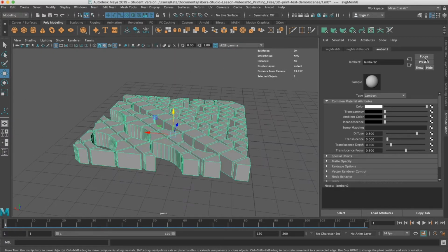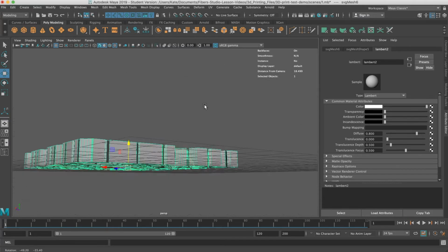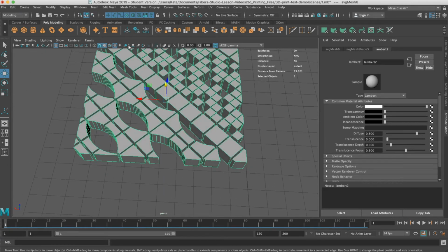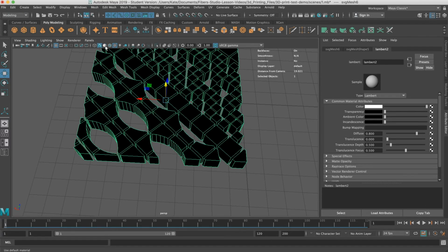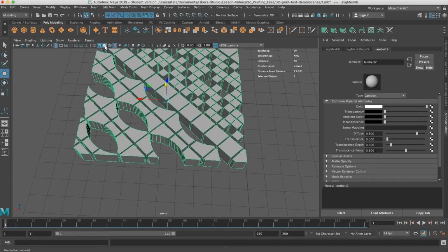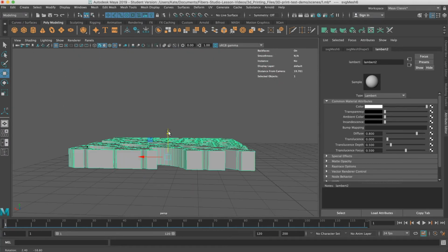There we go. Yeah, sometimes the color will not show. If you decide you want to change the color, and it's too dark to see or whatever, you have to make sure that this one right here, textured, is selected, and use this default material button right here, and it will bring it in as a darker color.